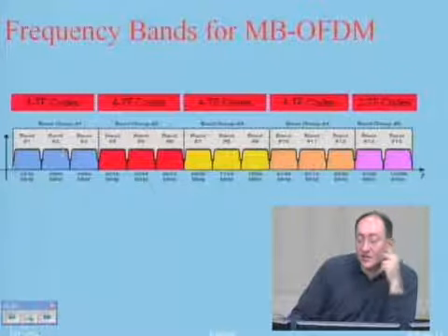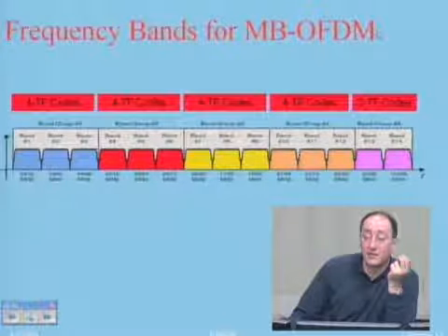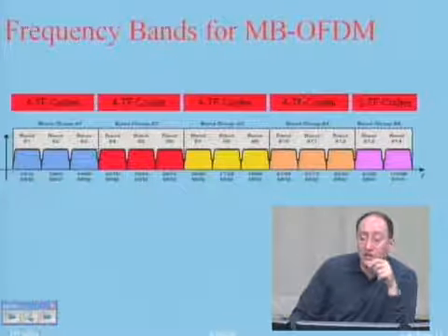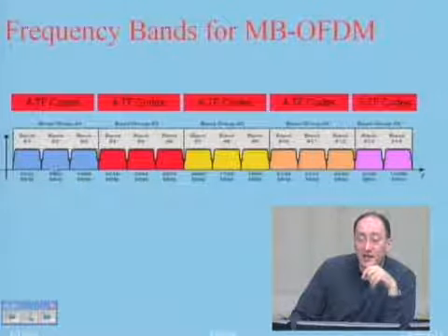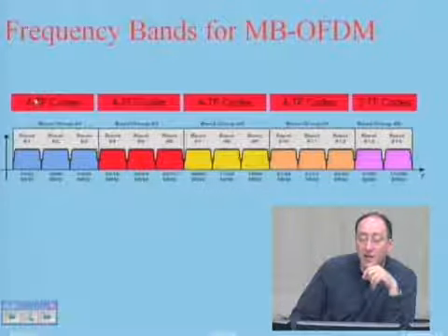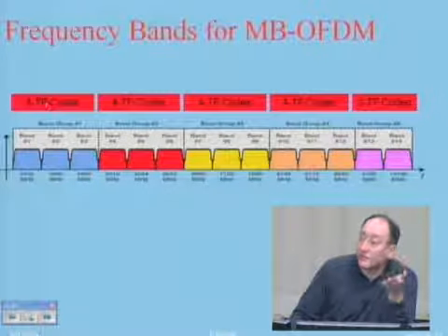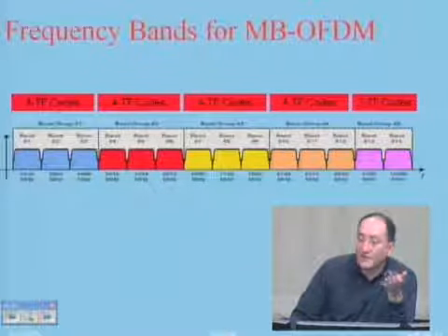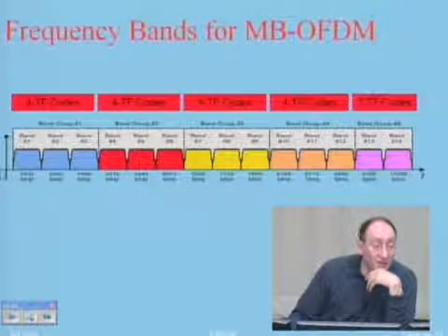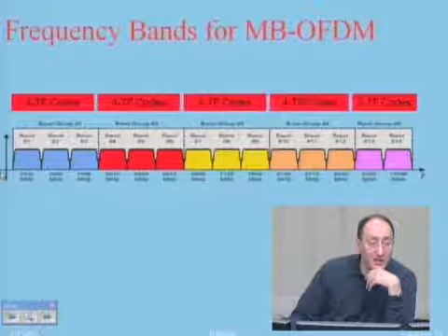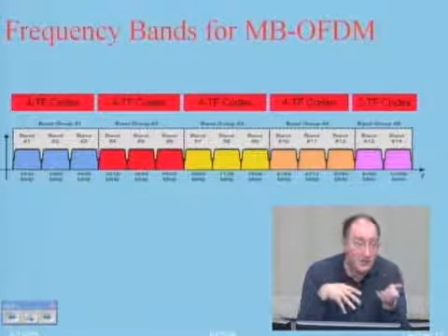What they do is that in each of these bands, they are using an OFDM signal. But in the OFDM signal, when I have 3 bands, they do the so-called time frequency hopping or time frequency jumping. It means that I send one symbol here, then in here, then in here, and then I come back to the first one. Okay? So while I'm changing the time, I'm also changing the frequency.